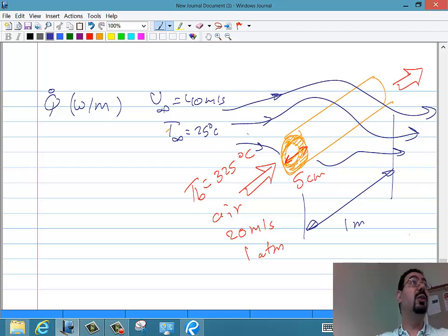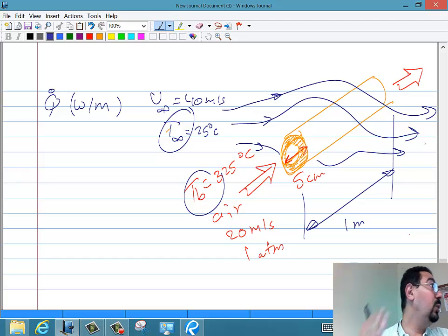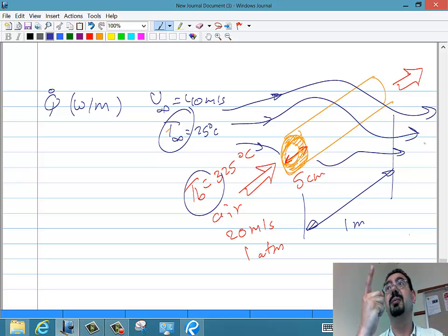the temperatures were given at the 2 extreme ends of the wall, and he asked for the Q, and we said the Q was delta T over R. It's the same thing. You have T infinity and you have T bulk inside. There is fluid inside, there is fluid outside, and the Q that will happen from the hot to the cold must be delta T over all the resistance. And there are 3 resistances, 2 convection and 1 conduction.